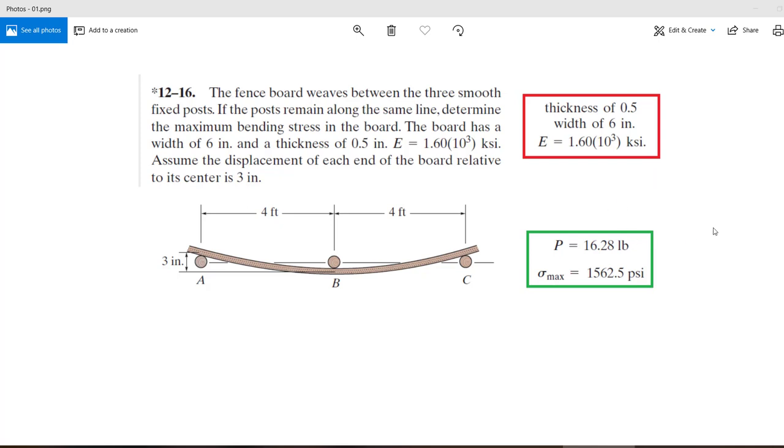Hello and welcome back. Up until now, we have solved this problem using the beam elements, 2D plane stress elements, and 3D shell elements. Now we want to get a little bit ambitious and put these pins and convert the linear analysis into a non-linear analysis. And we will see, using the frictional contacts, how the results would be different when we just apply the boundary conditions over here. And we're going to start putting these pins here instead of just the boundary conditions.